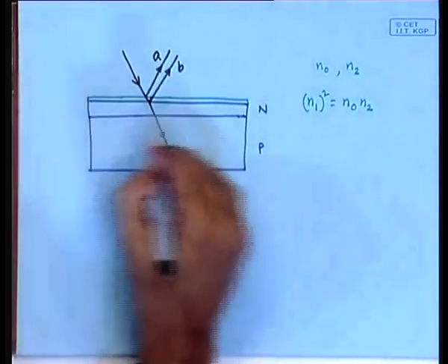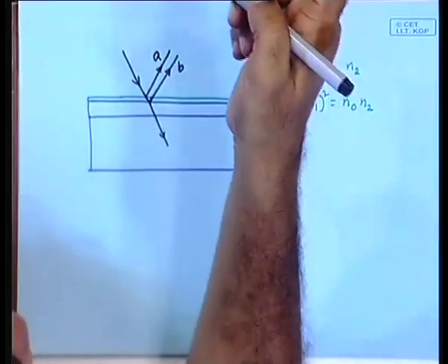Now, as I told you, the thickness has to be tuned to the specific wavelength, because it has to be about 1/3 of the wavelength. Now, do you choose it for red or blue or green? Violet? Not really, because some part in the red region is actually non-productive, because it has energy that is less than the band gap energy. Out of the ones that are productive, there will be some frequency which is maximally productive. Normally, this is tuned to that frequency, like blue, but not in the violet.